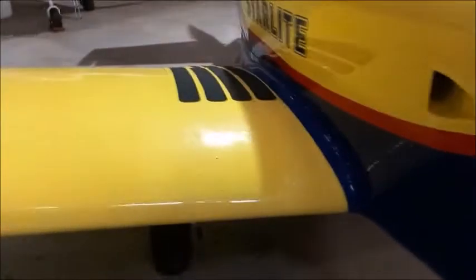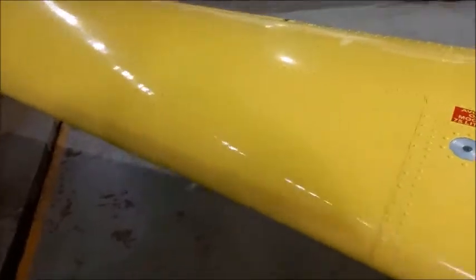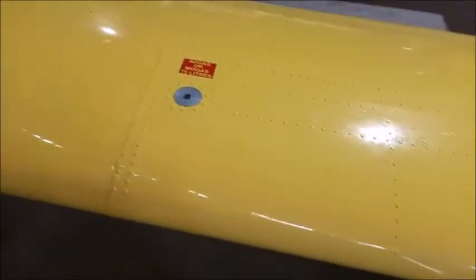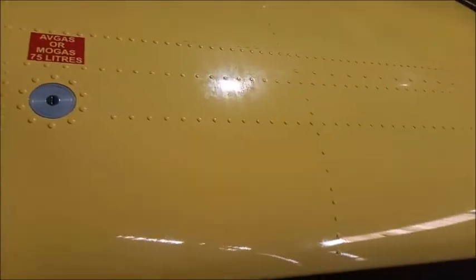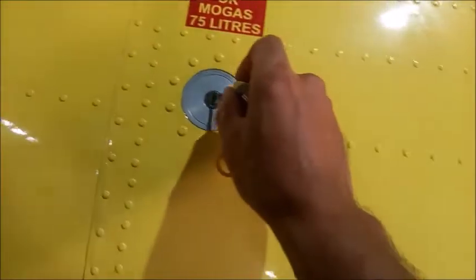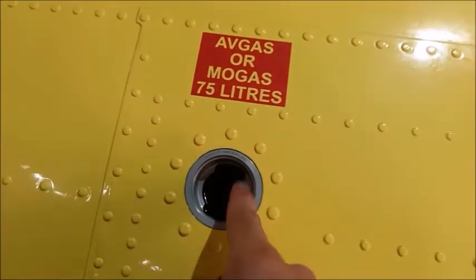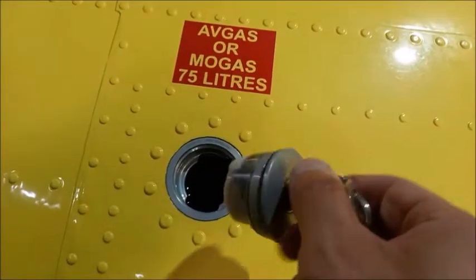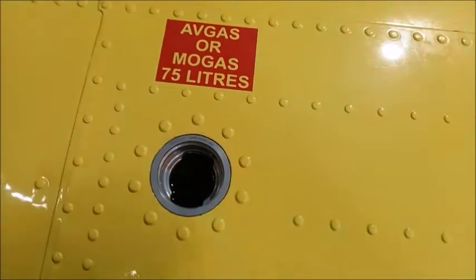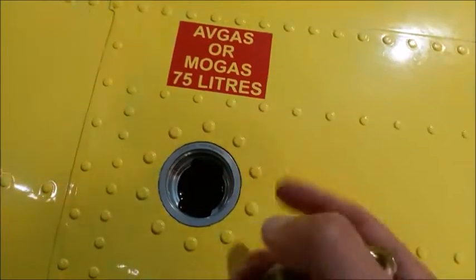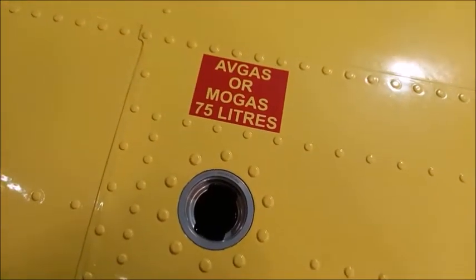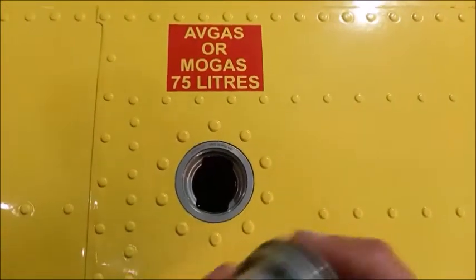And then we come and have a look. Over here we've got the air inlet, which will go to the air vent inside of the aircraft. We will also check to make sure that the leading edge of the wing is in good order, and that nothing has impacted and damaged it. What we will also do is check the fuel to make sure it's filled up. As you can see over there, it is filled up with fuel, and it's got a greenish color as well, so we know that is all correct. As you can see, 75 liters in each tank, one in each wing. It can be either avgas or mogas. That's quite a nice thing about the Sling 2s, while other aircraft are sometimes restricted to only mogas or only avgas.